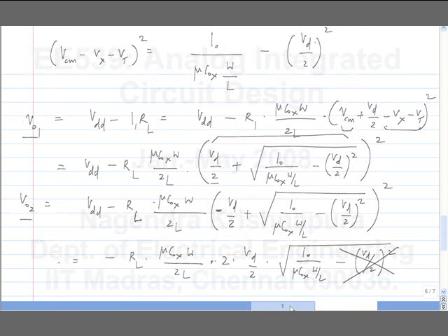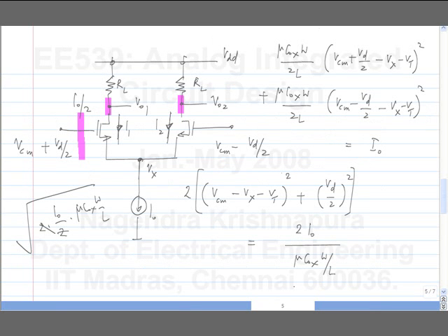Not many new things here, because I think you're at least familiar to some extent with differential circuits, but this is what happens, that the gain from VD to VO1 is something from here to here, and gain from VD to VO2 has the same magnitude but the opposite sign. So what does this say? VO1 and VO2 also swing equally and oppositely from the common mode voltage. If you apply a certain VD. Is that okay?